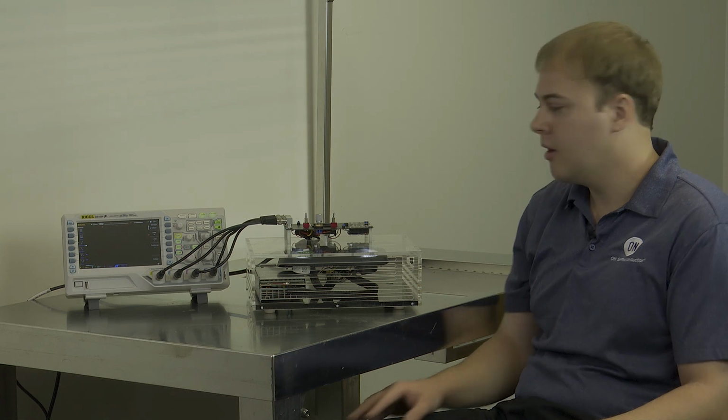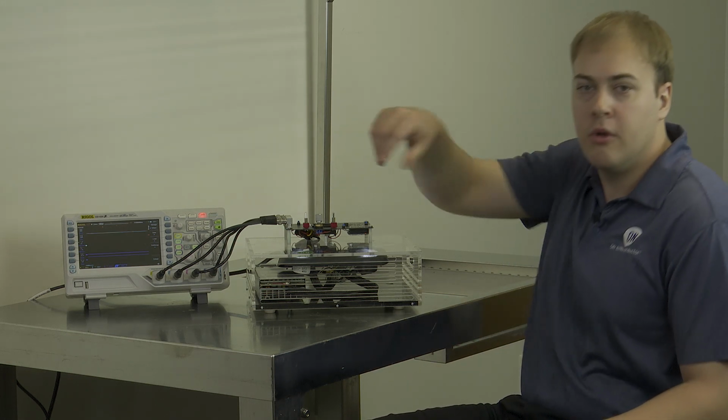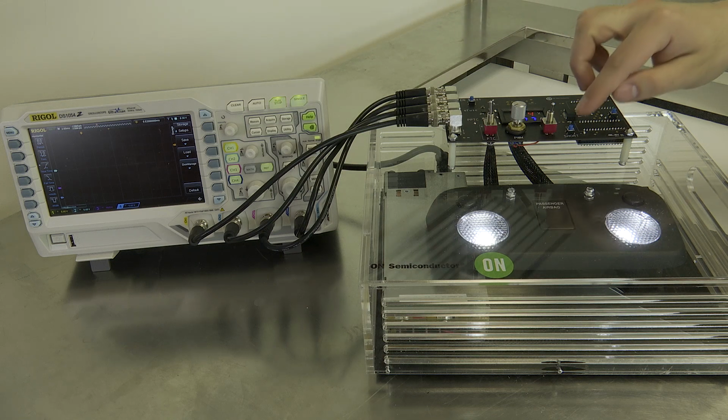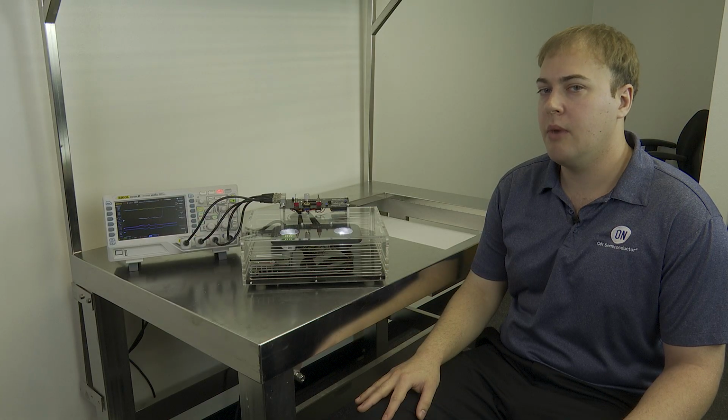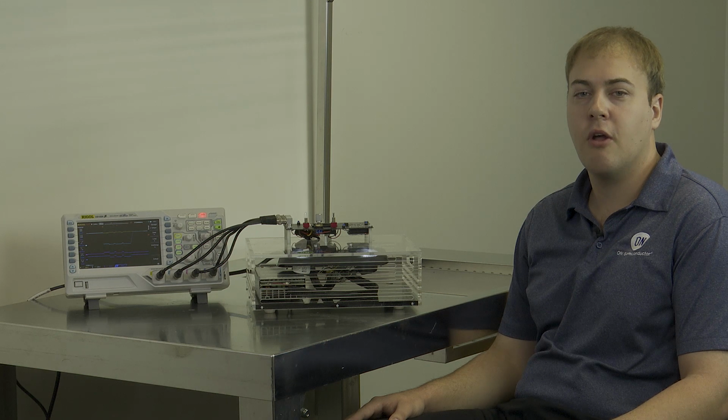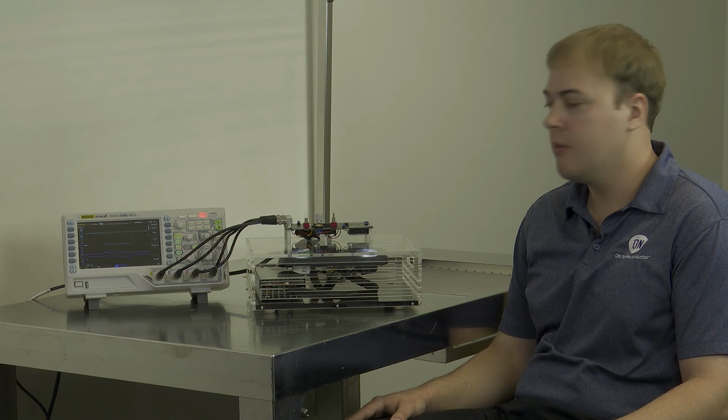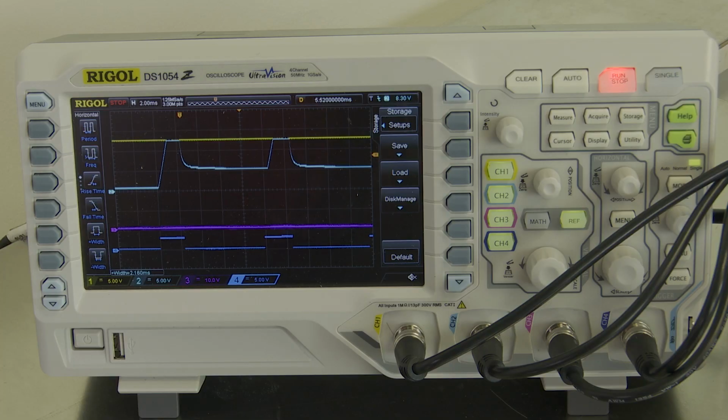First, I'll demonstrate what happens when there is a short circuit. Setting the switch to eFuse mode, we will press the output short button. The short circuit being generated is a chattering short generated by a microcontroller. Due to the fast response of the eFuse, the 12 volt input voltage rail does not go down. It's also important to note the level of current. Right now the current is 10 amps per division.